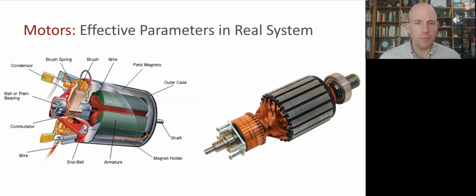And with this big complicated thing, it would be hard to measure the length or the magnetic field strength as that's changing as you move through the space, and so is the radius, which gets you to torque. But fortunately, we can capture the net effect of all that complexity in this lumped term, which we call the motor constant. And what that is really is the integral of all of the B, L, and R terms that will eventually multiply current to get torque or multiply velocity to get back EMF.